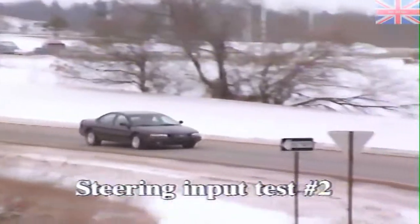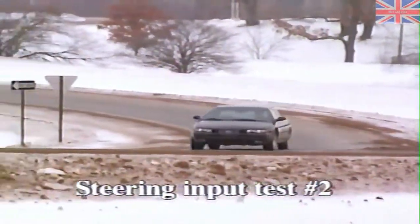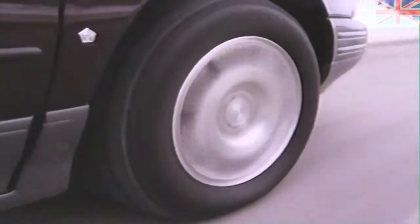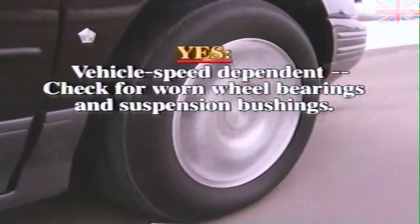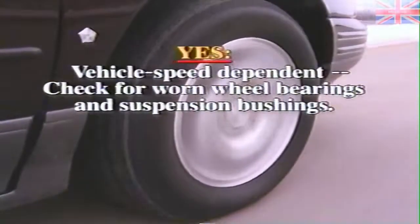The second steering input test is used to isolate problems that occur only when turning. Perform the previous procedure, only this time coasting with the car in neutral. If noise or vibration are generated, the problem is independent of engine speed. Check for worn wheel bearings and worn suspension bushings.